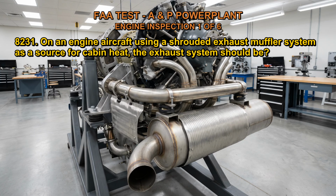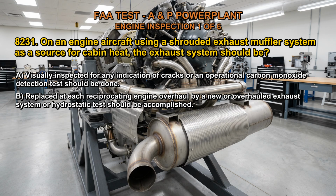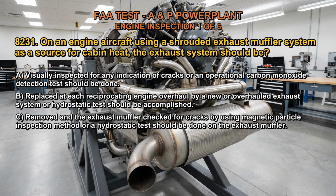8231. On an engine aircraft using a shrouded exhaust muffler system as a source for cabin heat, the exhaust system should be A. Visually inspected for any indication of cracks or an operational carbon monoxide detection test should be done. B. Replaced at each reciprocating engine overhaul by a new or overhauled exhaust system or hydrostatic test should be accomplished. C. Removed and the exhaust muffler checked for cracks by using magnetic particle inspection method or a hydrostatic test should be done on the exhaust muffler.